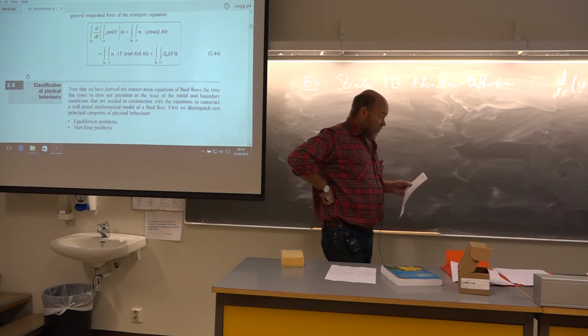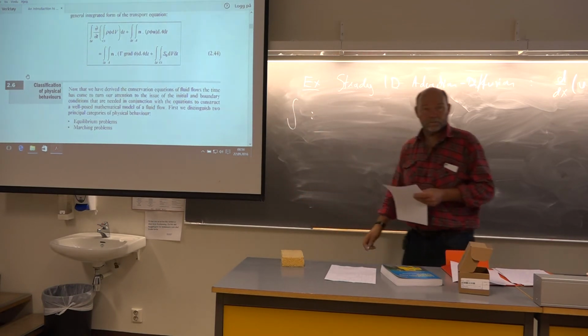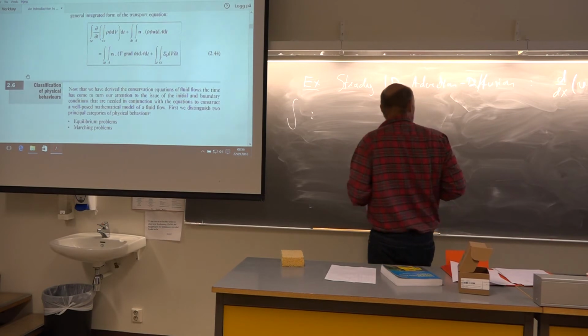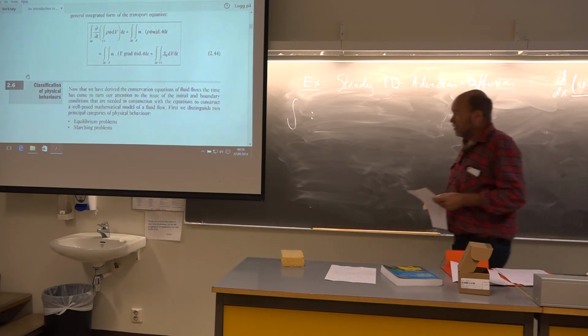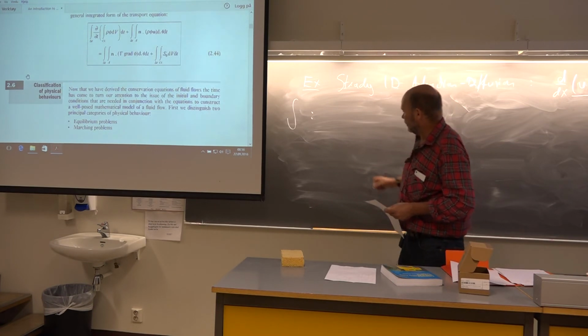So this is the equation, and now take the integral of this equation. And here, this advective term is written now on a conservative form. You have the derivative in front of it. So that's very convenient when you want to do a space integral. All these derivatives, they just disappear. So we will be left with just the parentheses here. But it's a question of the boundaries.